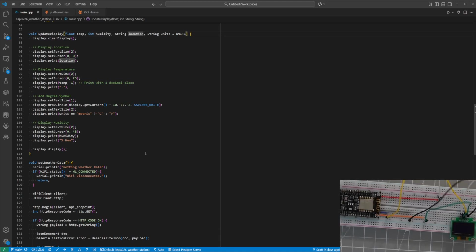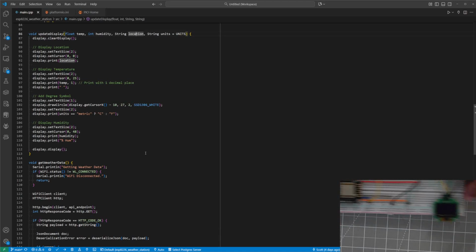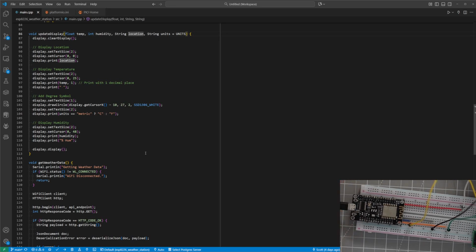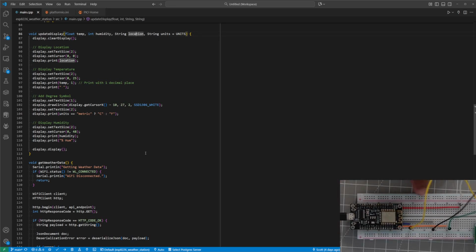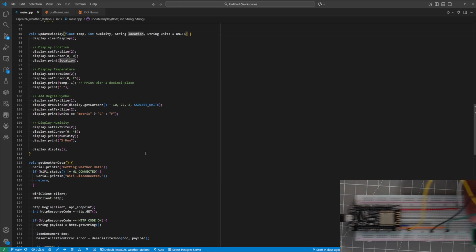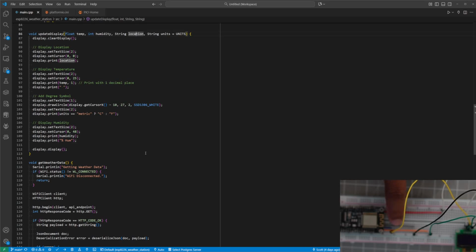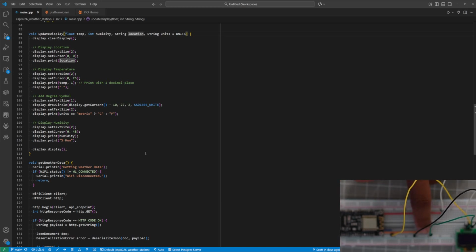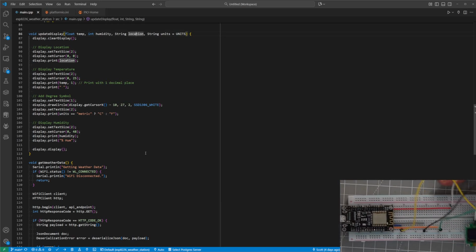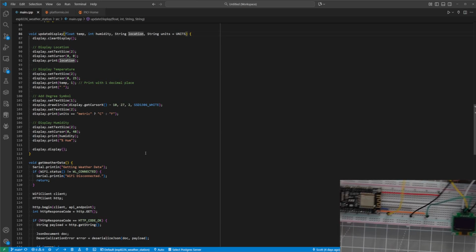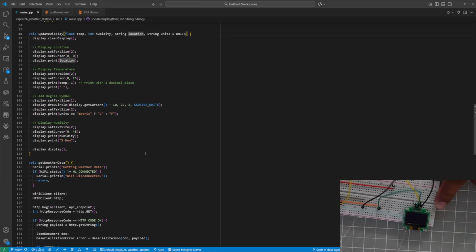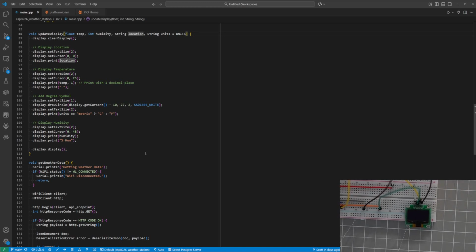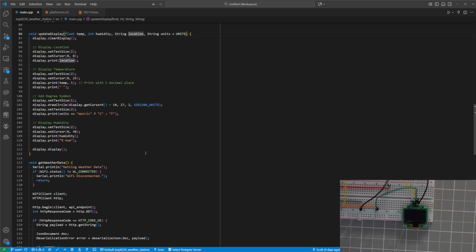And if I plug this in, and I want to mostly focus on the OLED, and I guess I can show an overview of everything here to make it a little bit easier to see. But again, red is 3.3 volts running to the VCC of the OLED screen. Gray is D1, the clock line, sorry. Blue is D2, the data line, and orange is ground, running to ground on the OLED screen here. So let's focus mostly on the OLED screen here. I wonder if I can get it a little bit tighter on this.